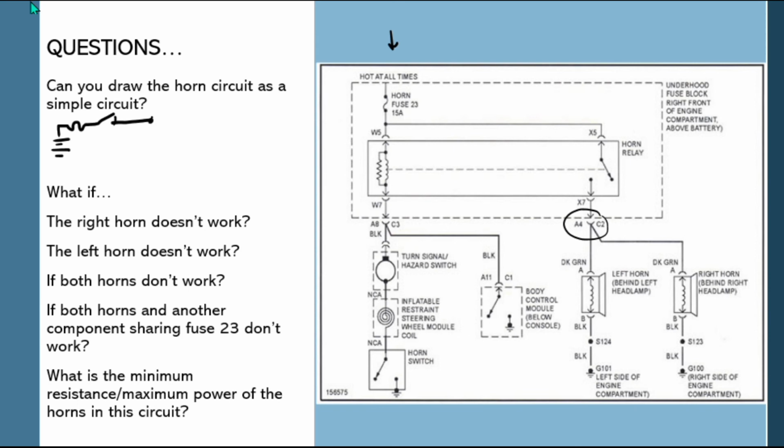And at that point, I'm splitting between my left horn, which will make a resistor, and my right horn. And then I come back to ground. So they're going to connect up and we don't have any more voltage drops all along. And there's the horn circuit. So it's very easy to see that it's a simple parallel circuit when I redraw it.